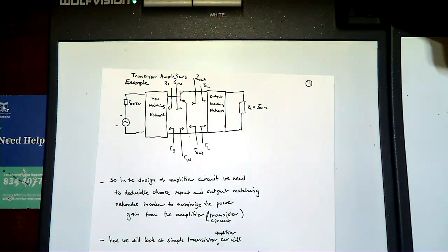This won't have infinite input impedance for all frequencies, right? And it's also got a finite transfer function. Anyway, you've been taught this in one of your other classes, I bet, right? And you've designed a power amplifier. What I suggest that you do is look up gain bandwidth product, right? And then actually see at what frequencies can I actually use this circuit in order to do amplification.